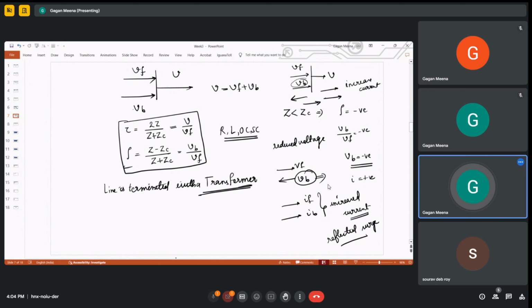The resulting capacitive voltage distribution can be represented in a similar manner as for a string of suspension insulators. Just as we did that. The magnitude of the surge voltage can be reduced by providing a short cable between the overhead line and the transformer.